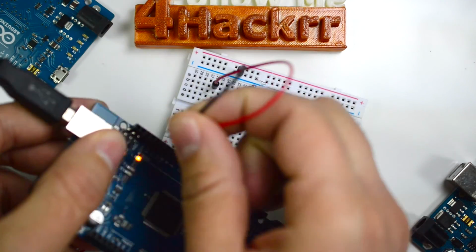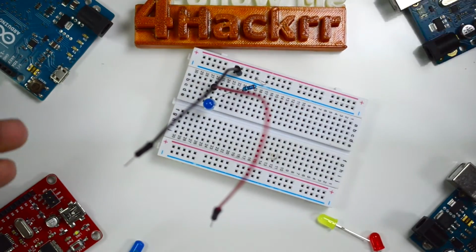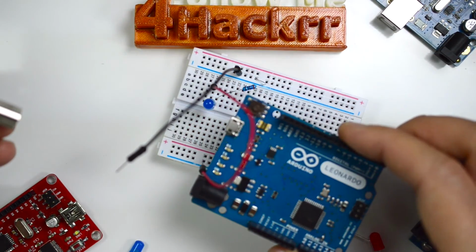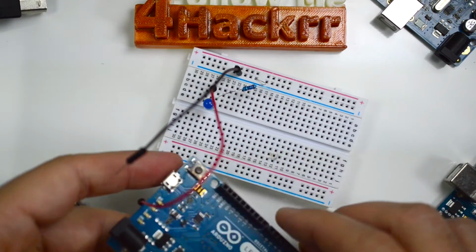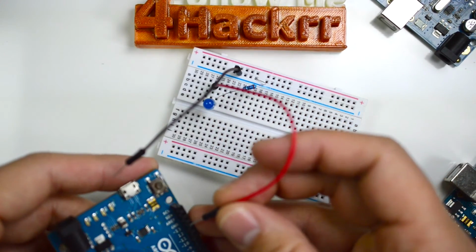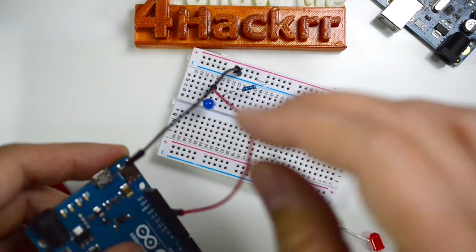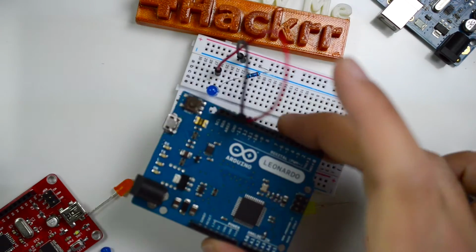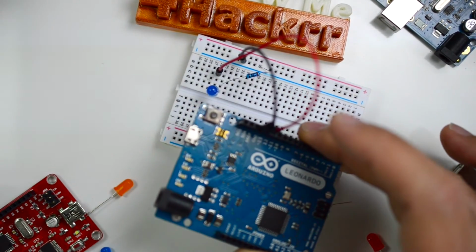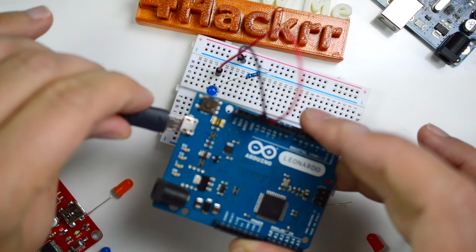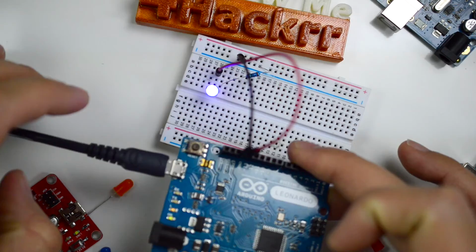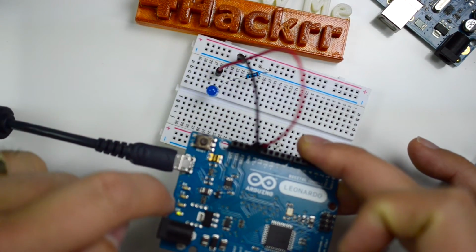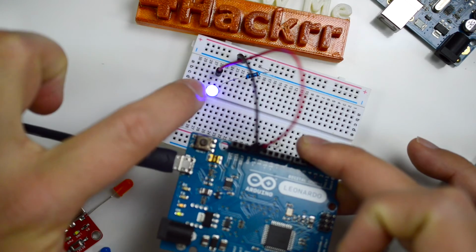So now we can just unplug this from here, unplug the power, and I have one more board, which is the Arduino Leonardo, and I will do the same thing. So let's first connect the pins. So 13, and now I'm going to connect ground. Okay, and now we have to apply power, and here's the power, and you will see the same behavior. So it's blinking, and it's also blinking on the board on the L LED, external and the L.